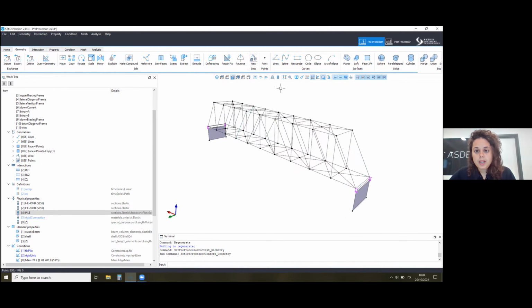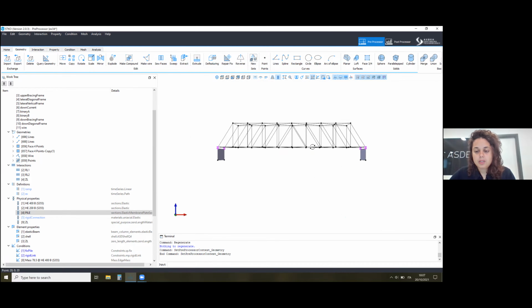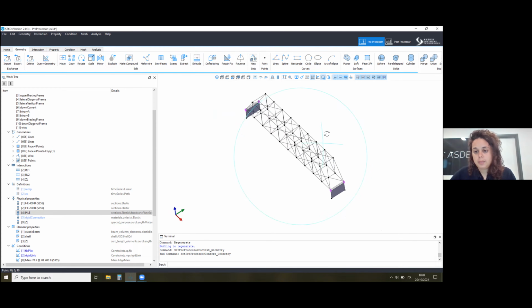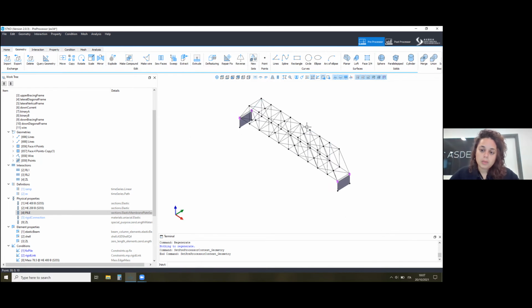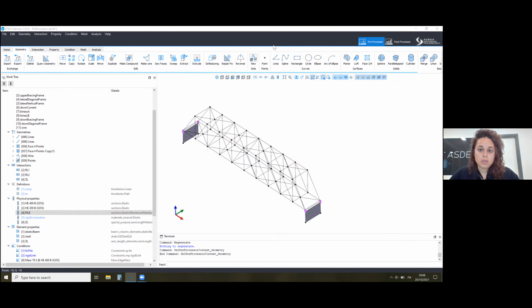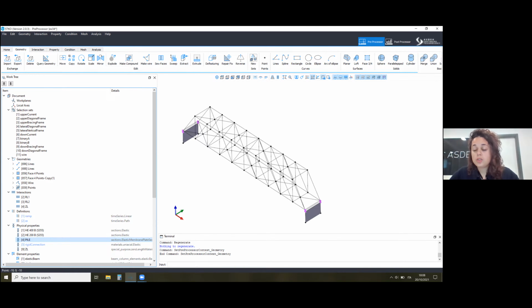You can create a 3D steel frame structure in the same way that you create a 3D concrete frame structure. We already discussed this when we talked about infill panels: our model has trusses, so it has edges in the geometry. Maybe you're interested in not joining elements at their intersection. So whenever you model them, remember to use the command make wire instead of the command merge. I used one command in one model and the other in another, so I can show you the differences.